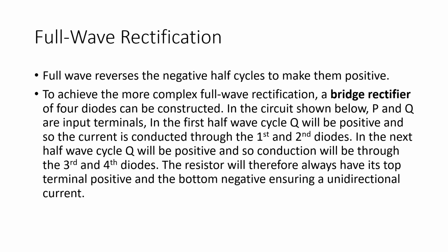When it comes to full wave rectification, this is where it becomes a little bit more complex, because it involves full knowledge and understanding of what is taking place. In full wave rectification, we are rectifying both the negative portion and the positive portion. So what you're essentially going to do is take the negative and make it become positive. That's what we're really doing in full wave rectification.